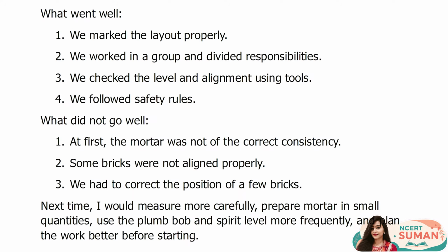What did not go well? 1. At first, the mortar was not of the correct consistency. 2. Some bricks were not aligned properly. 3. We had to correct the position of a few bricks. Next time, I would measure more carefully, prepare mortar in small quantities, use the plumb bob and spirit level more frequently, and plan the work better before starting.